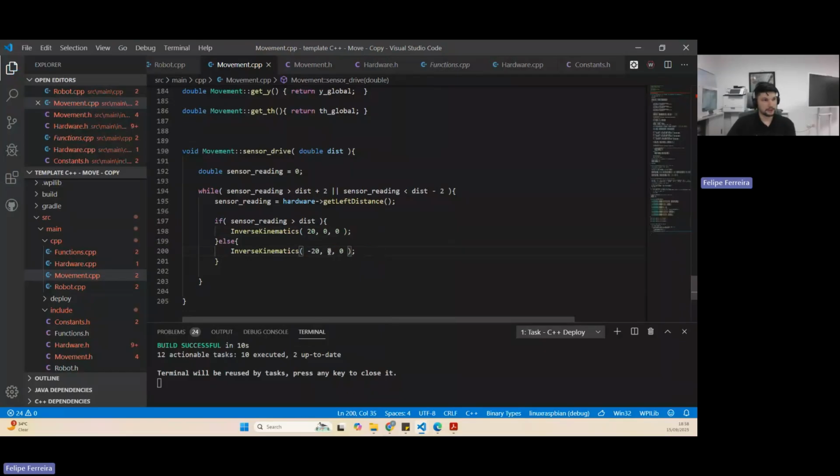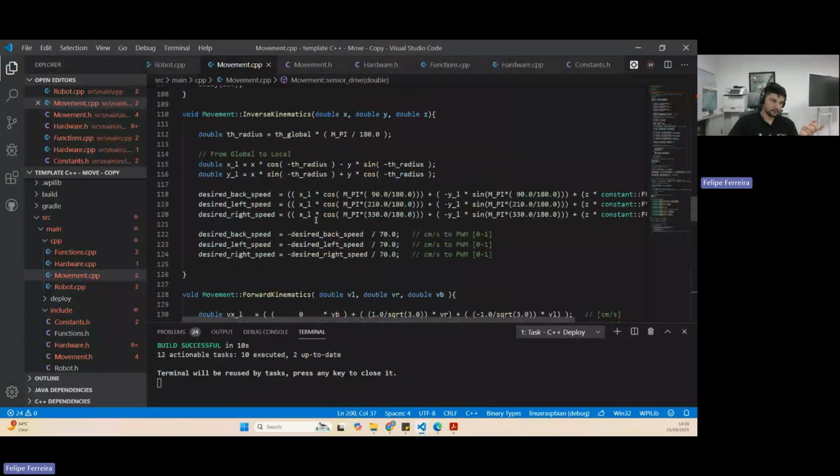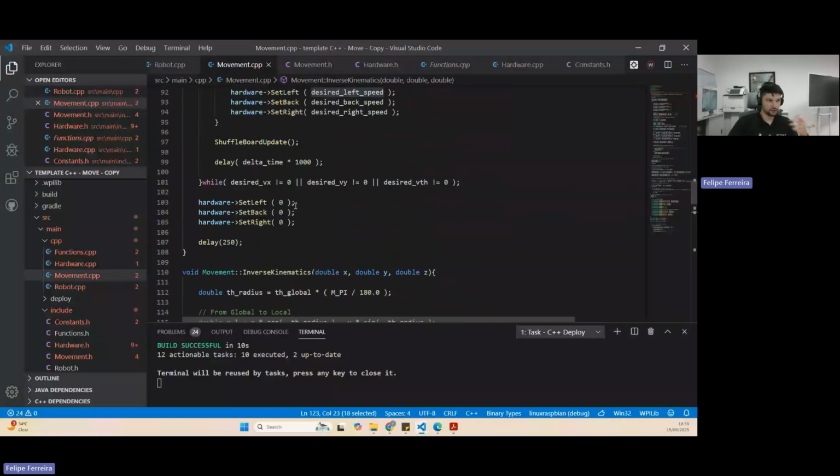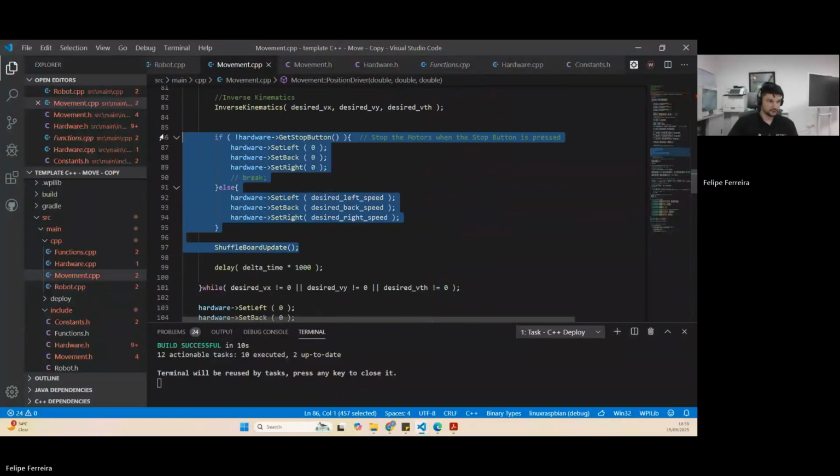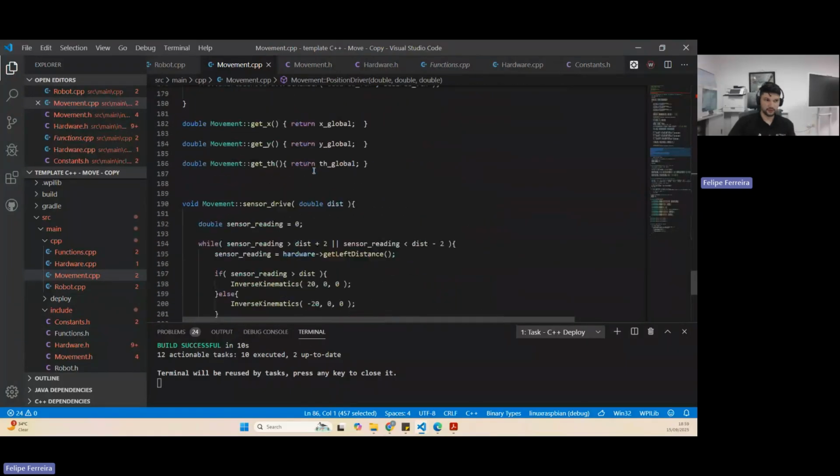Backward, minus 1. With inverse kinematics, we calculate how much should be applied in terms of PWM to the wheels to perform this move. After kinematics calculates these, I apply them to the motors. Same as I have mentioned.